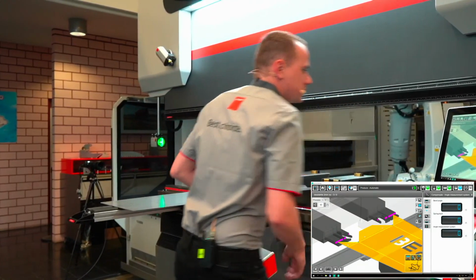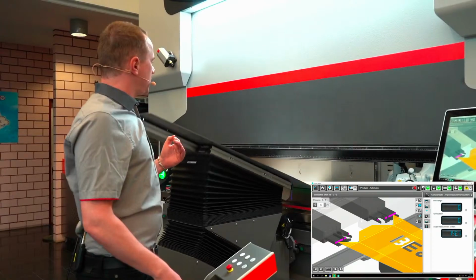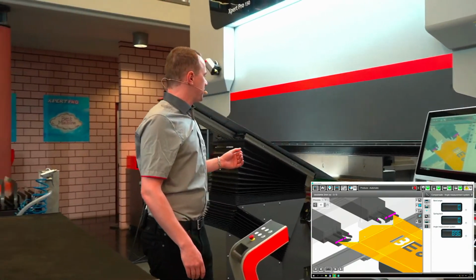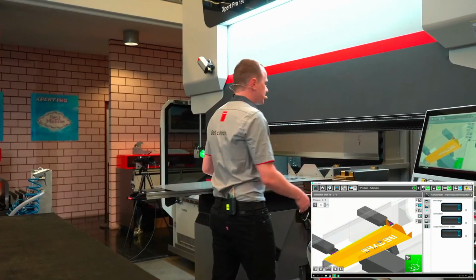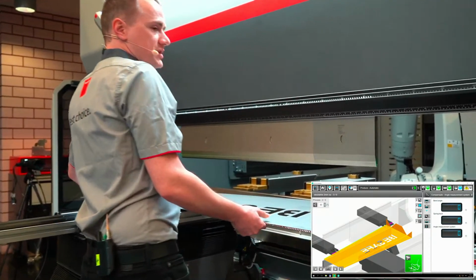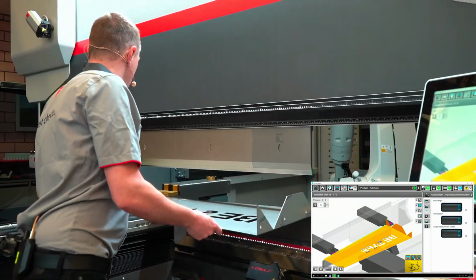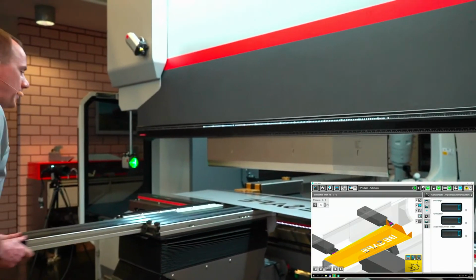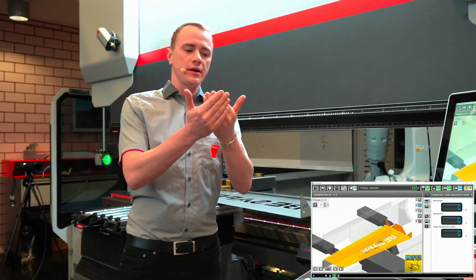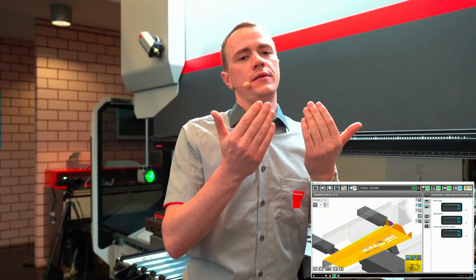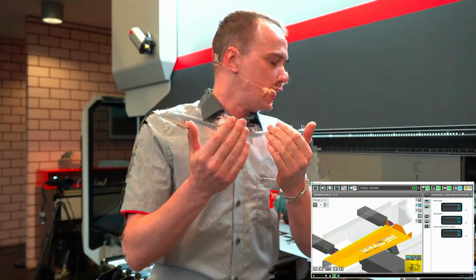Now, the first bend is with the laser angle measurement system on, using the spring back from the database. On the next bends, the laser angle measurement system is on, and we're going to physically measure the actual spring back of the part. You can see it especially on the bending aid, because the bending aid is absolutely following the upper beam. So what we do is we go to the target angle, we release the part and measure the actual spring back. We really release it to have the absolute correct values, and then rebend it.